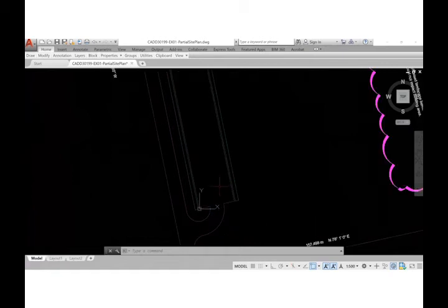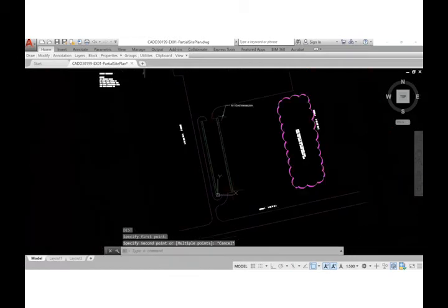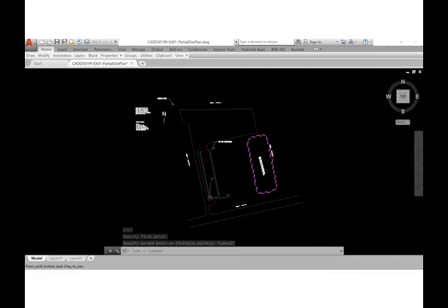So I wonder whether they're using really meter here, right? Instead of millimeter. So I can check DI. And let's see, if this is a driveway, how big was this drawn? Okay, it's using 6,500. That couldn't be meter, right? So that should be millimeters, 6 meters driveway, right? So the notation is in meter, but the drawing is in millimeter. Okay, so that's something that you'd like to find out. Very important.